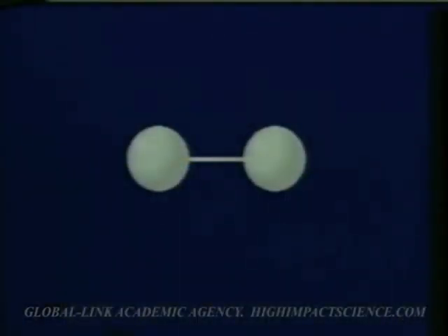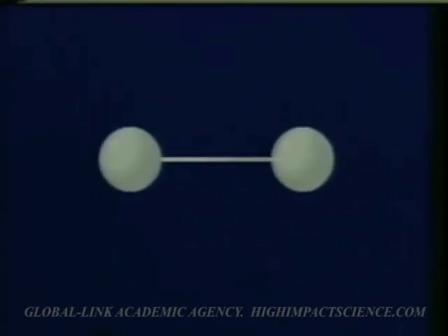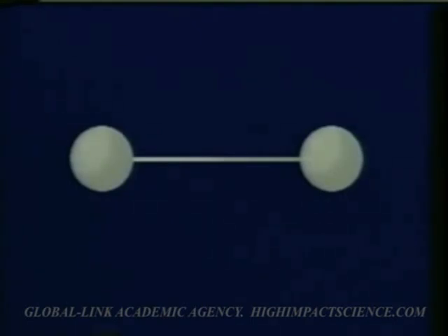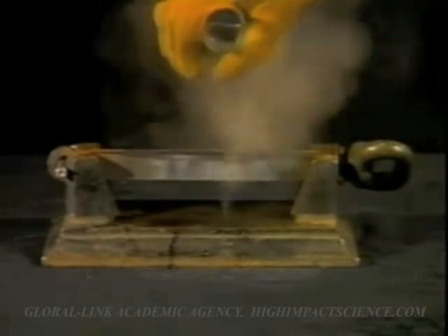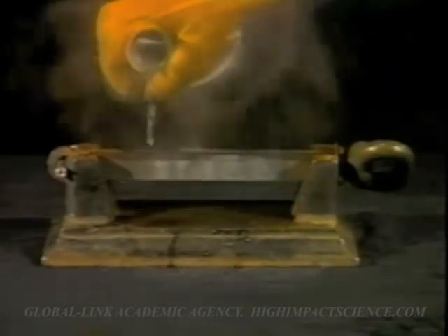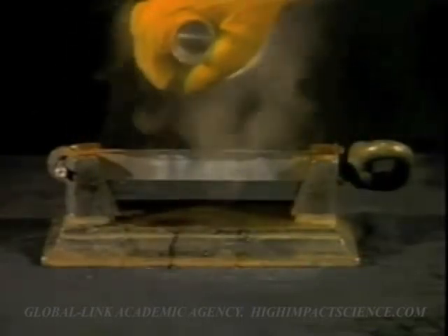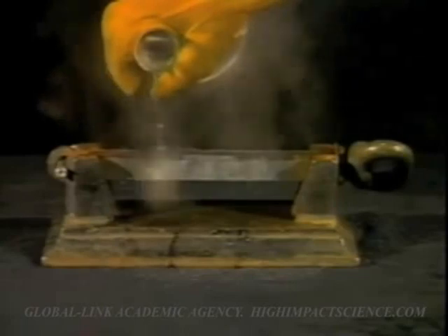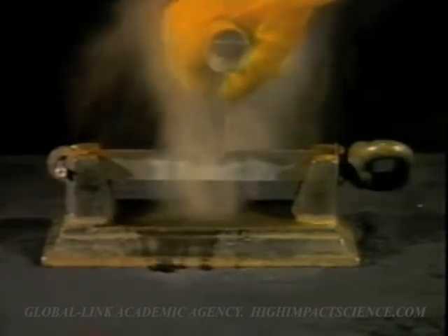As a material is heated, the frequency and amplitude of molecular vibration increases. The result is thermal expansion. When cooled, the molecular vibrations decrease and the material contracts. The forces generated by the summing up of individual molecular contractions can be quite significant. For instance, the force needed to snap the iron rod in this experiment is approximately 4,000 newtons, a force roughly equivalent to that needed to lift a 1,000-pound mass.